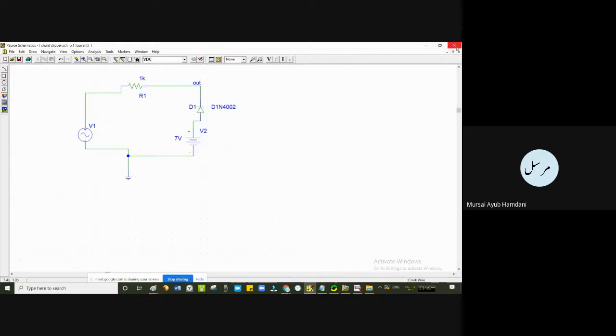Now the Zener diode behaves similarly to any common diode in the forward bias condition. However, in the reverse bias condition, its breakdown occurs early due to Zener breakdown at the Zener voltage. For the particular Zener diode that we take, -5 or 4.9 is the value where the breakdown will occur. So this early breakdown makes it useful as a voltage regulator, as we shall see, and it also helps in the clipping circuit, as we shall see in the clipping example also.